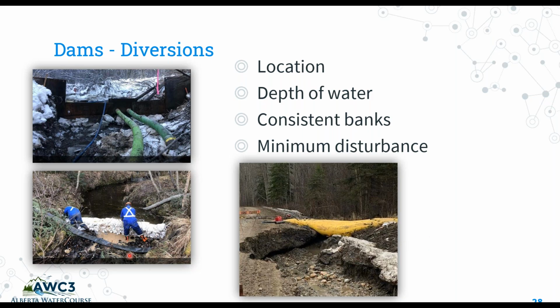I've got 3 pictures of dams. You can use sheet pile dams. Sheet pile dams are nice when you've got sediments on the upstream side of your crossing. When we talk about hanging crossings, a lot of times a fluvial creek may acquire sediment above the crossing. You can look at sandbag dams. I've got an aqua dam shown here.